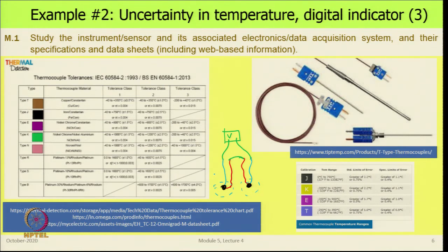One, so this is say a higher temperature T h, this is the lower temperature T L, then the EMF produced is proportional to the difference T h minus T L. So, if we can measure this by measuring a change in the EMF, from there we get delta T, which is the difference of these two temperatures.